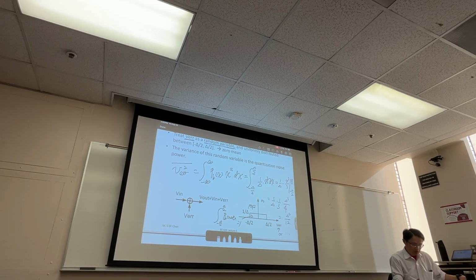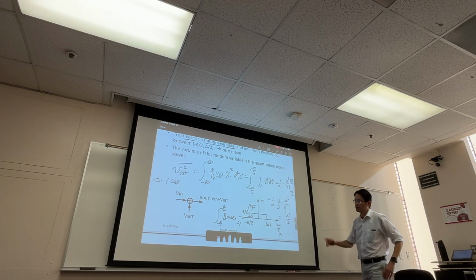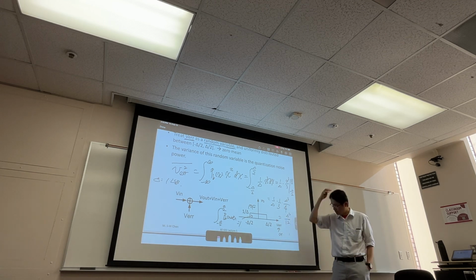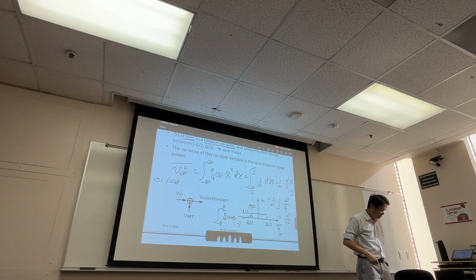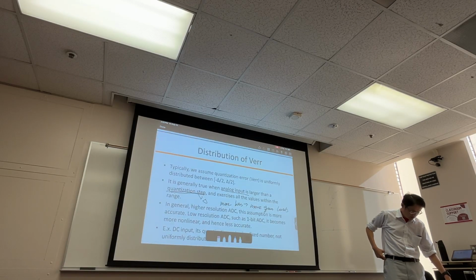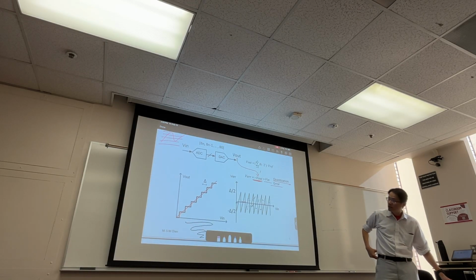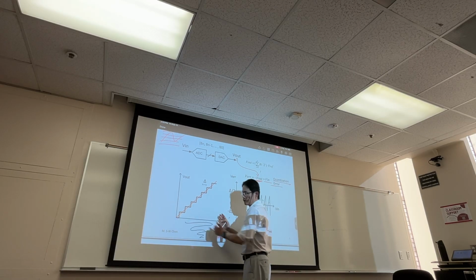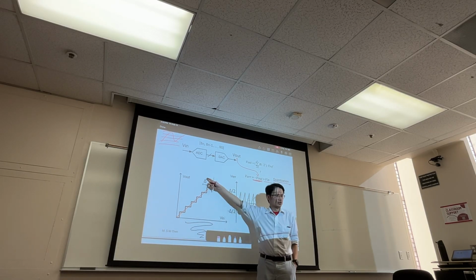Okay. I forgot to mention this delta in the ADC world. Sometimes we also call this 1 LSB. Okay. So one least significant bit of that step. So 1 LSB is 1 delta. Okay. And in fact, if you look at the full range here, what's the relationship between the full range and the delta?